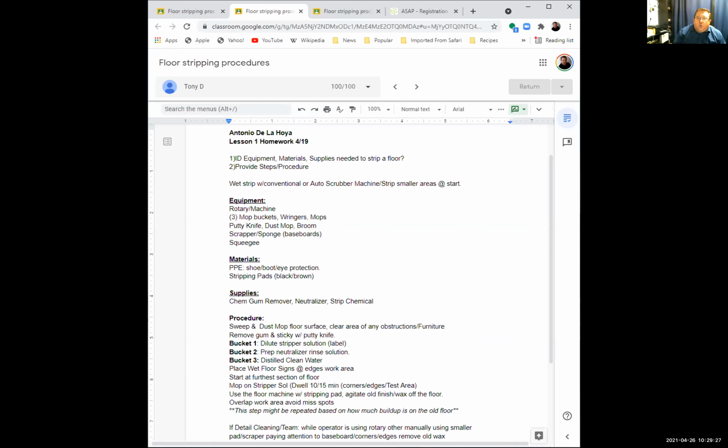Okay, so that's one trick. The other trick is using ceiling tiles. If they have a drop ceiling in an area, you can use the ceiling tiles. Those ceiling tiles measure 2 foot in width and 4 foot in length. You'll see this a lot in classrooms. If they are rectangular, they're 2 by 4. If they're square, they're 2 by 2. Count your ceiling tiles and then use those numbers.